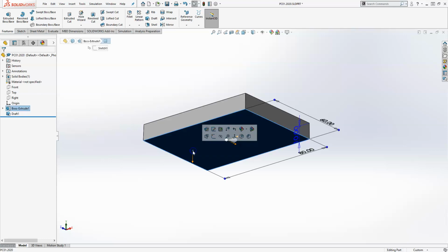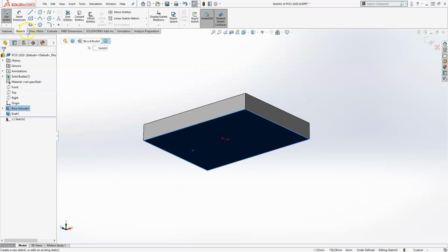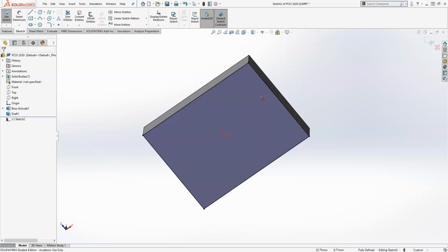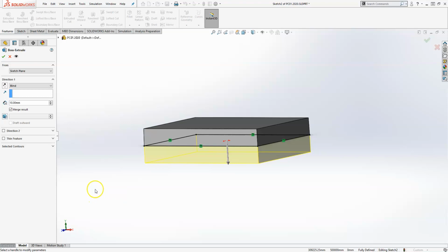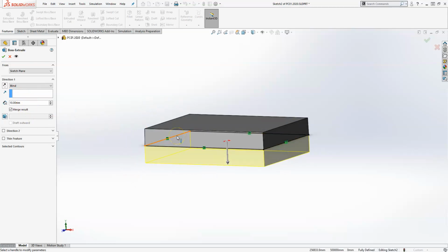So now we'll create another sketch, and we'll create the bottom half. So I'm sketching on that bottom surface, and instead of actually drawing anything, I'm going to use that convert entities. And because I had selected the face, it takes all the outer edges, and you'll notice there's 4 black lines there, so we're good. So now we can extrude. So I'm doing this part in two different extrudes, so I can show you I'm drafting in 2 different ways.